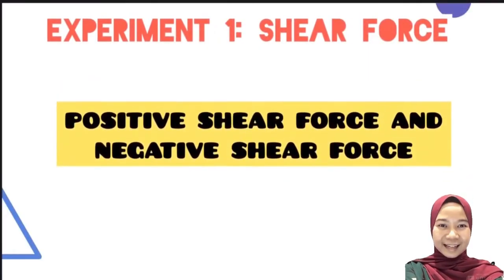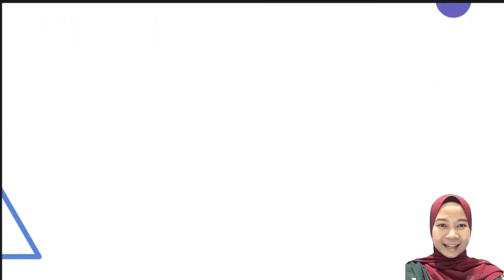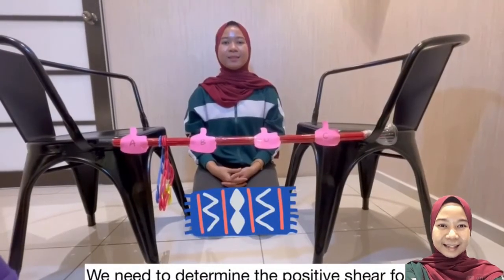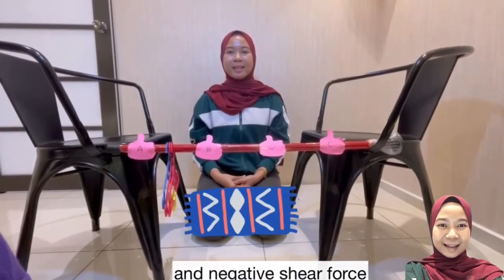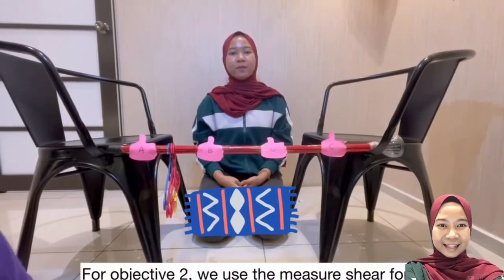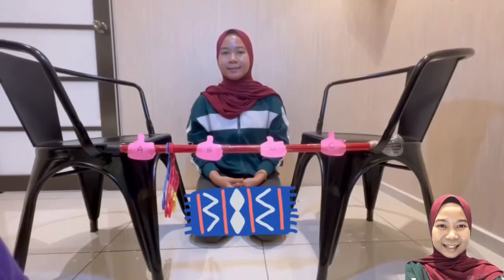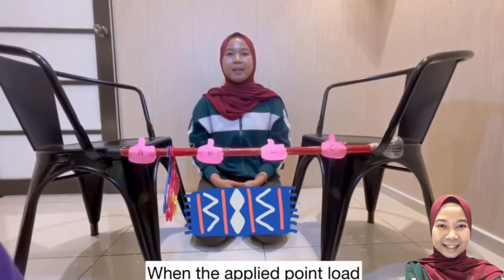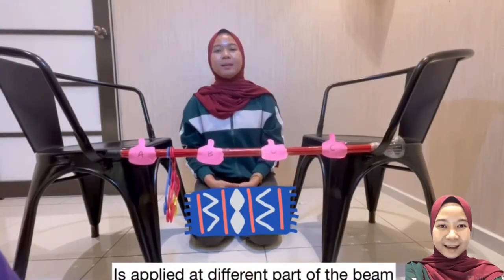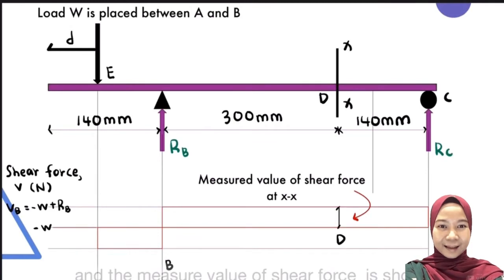Hi, Shahida here. I will show you the second objective of the shear force experiment. Next, we need to determine the positive shear force and negative shear force. For objective 2, we use the measured shear force from the previous part and draw the shear force diagram for each case. The measured shear force will be positive or negative depending on where the point load is applied on the beam. Take case 1 as an example. This is the shear force diagram and the measured value of shear force is shown.